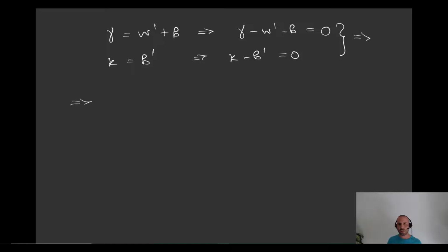In this case, we would need to multiply the shear deformation with a variation of the shear forces in order to obtain work, and then integrate over the domain, of course. So the first equation, we're going to multiply the residual form of the kinematics equation related to the shear deformation with the variation of the transverse shear forces, and then integrate this over the domain 0 to L, and this is going to be equal to 0.